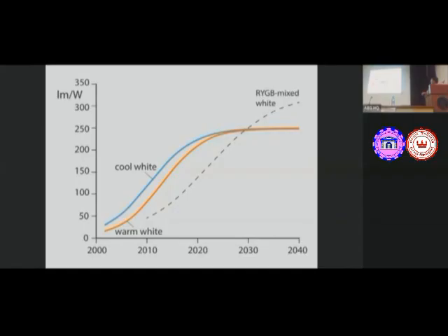So these are the lighting facts. If I go over the backside of any box of a lamp, we do get different data. Out of that, this data is not available in India, but this data is available in the European or American market, where they can very easily see what is the light output, what is the efficacy, as well as from the warm white section to the cool white section where it ranges. You can see there is an arrow that shows you what will be the color of the light. Okay, and this is the energy chart that shows the characteristics of the light.